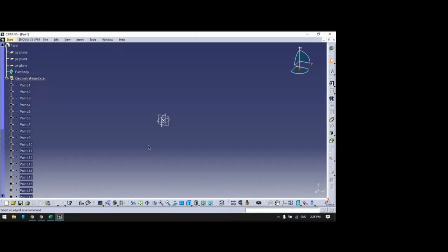Sir, so we need to project the airfoil that we have imported and delete the imported ones. So first I can select this fit all in so I can see the points and lines clearly. Next step, how to project it? Select a plane. Which plane? The plane which is parallel to the XY plane. Yes, XY plane. Then go to sketch.